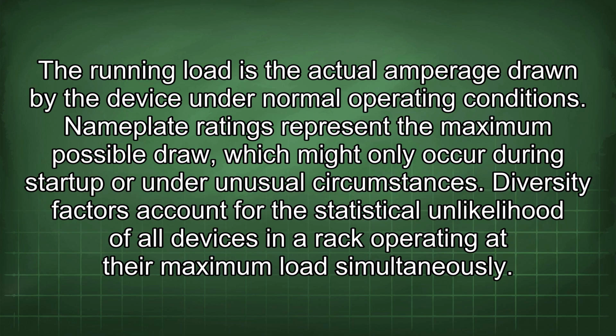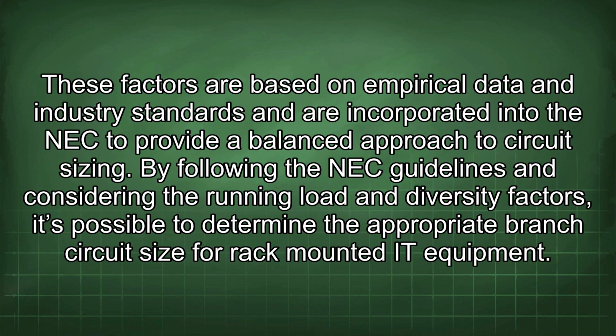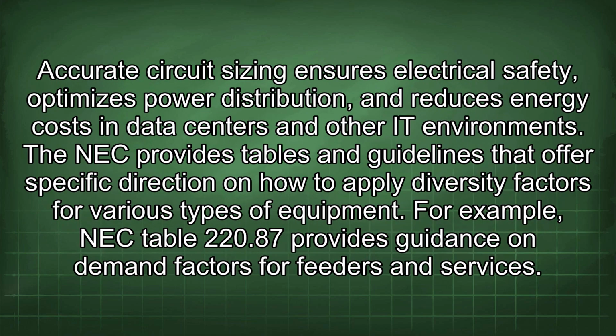Diversity factors account for the statistical unlikelihood of all devices in a rack operating at their maximum load simultaneously. These factors are based on empirical data and industry standards and are incorporated into the NEC to provide a balanced approach to circuit sizing. By following the NEC guidelines and considering the running load and diversity factors, it's possible to determine the appropriate branch circuit size for rack-mounted IT equipment. Accurate circuit sizing ensures electrical safety, optimizes power distribution, and reduces energy costs in data centers and other IT environments.